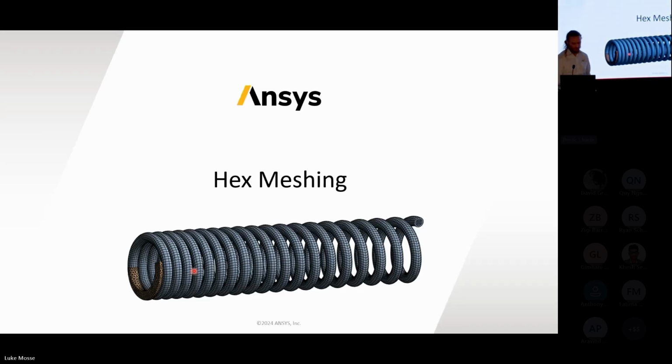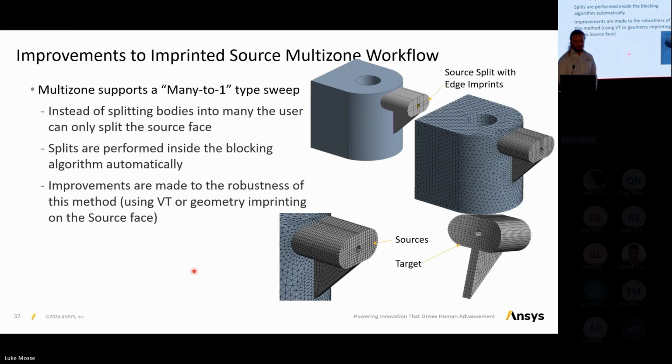Hex meshing. So there's a few nice updates here. One of them is just making multi-zone generally a lot smarter, so you have to do less messing around with all the options in the multi-zone mesher. The multi-zone mesher is great for giving us hex meshes on complex geometry.